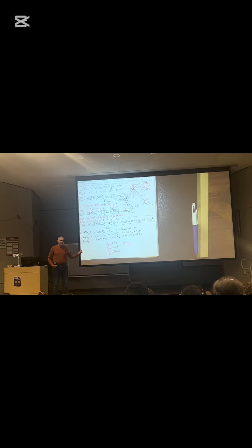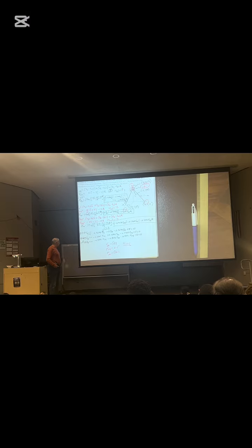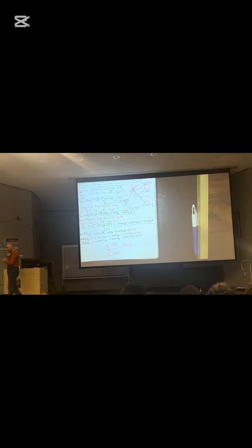I would say you'd write 13 kips in compression, 6.5 kips in compression, 6.5 for PB in tension. I would like for you to tell me that so I know you know what the hell you just calculated. It's one thing to calculate, but it's another thing to interpret what the hell the calculation said. So, on a question similar to this, are you asking for the magnitude of the forces or the forces themselves? No, the magnitudes of the forces. 13, 6.5, 6.5.